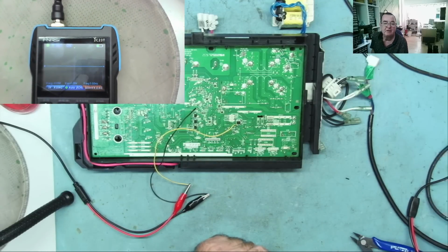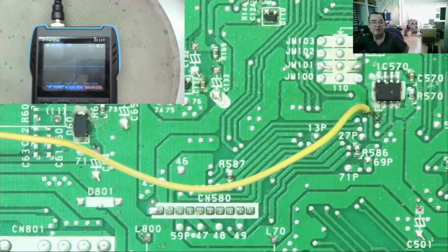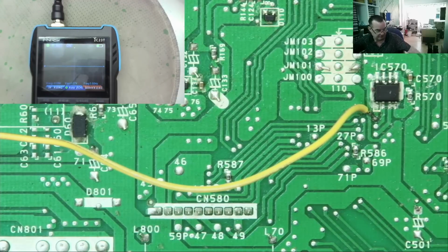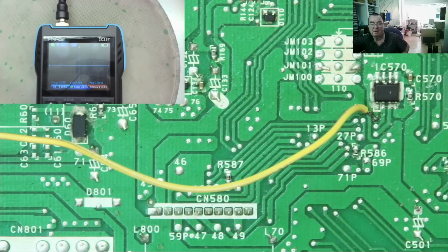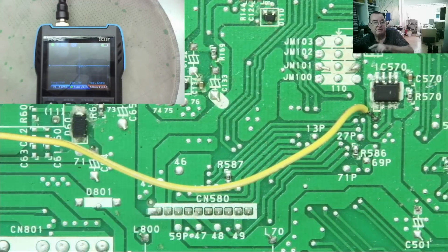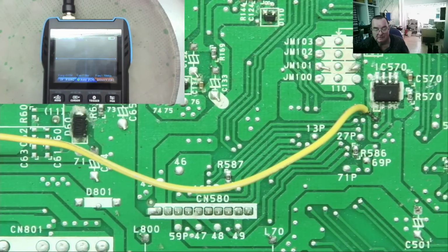Let's have a look to see if we have any activity on the chip select pin. Okay, we know the processor has power, so I'm not too worried about leaving the current limiter in. I could put a higher wattage bulb in this, maybe 100 watt, but I'm not too worried about that at the moment. Let's see what happens on the scope. Okay, I heard something go click. I think that's a relay. There's relays on this. Yeah, you click back off again.